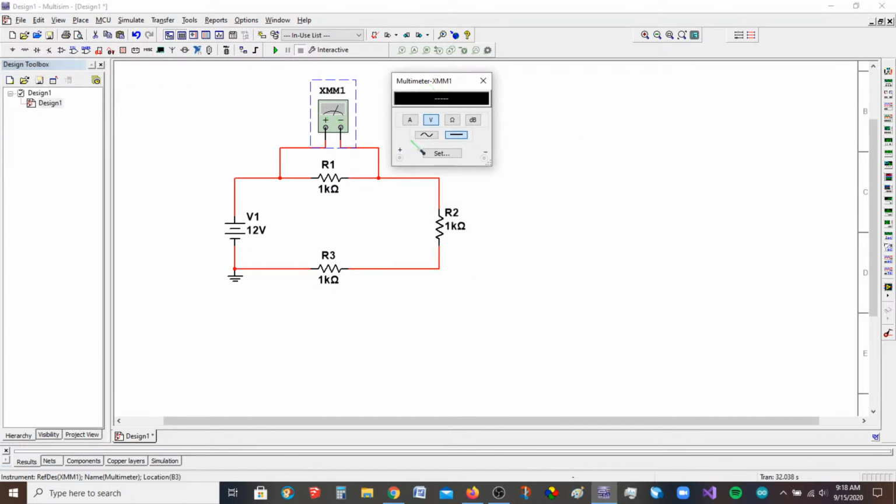Okay. Now, it is a multimeter, so this does an ammeter function, a voltmeter function. It does resistance measurements, and it also does some dB, some decibels for more AC work, okay, and signals. So we are going to use these three functions: the ammeter, the voltmeter, and the ohm meter. Okay, so right now I'm measuring voltage, so I want to make sure I'm on voltage, and then you select whether you're in AC or in DC. Now this is DC volts.